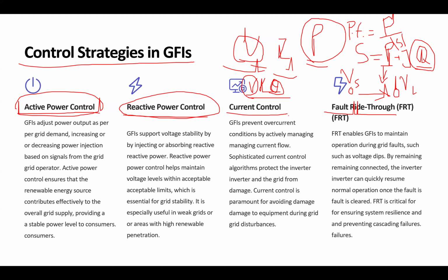Okay, if we need a higher Q, that means we have lower capacity left to transfer active power, meaning the power factor is low. So what we do is use compensation, using a capacitor or inductor based on our situation, to compensate the amount of reactive power. We want to reduce the Q so we have more capacity to increase the P, which we need. This is the concept of the power factor in the power system. Did I answer your question?